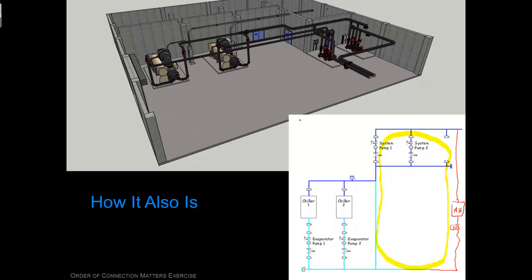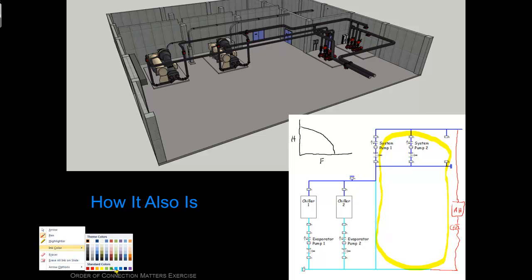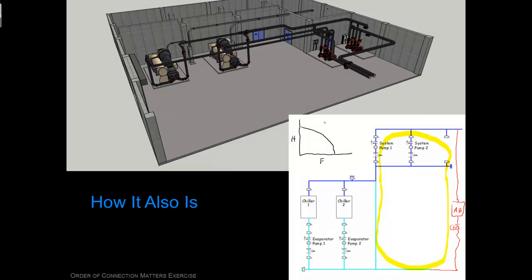So if you remember anything about pump curves at all, it's basically a plot of flow on this axis versus head or pressure on this axis. And for a fixed speed with a fixed impeller size, the pump is going to operate on a performance curve, the shape of which is purely a function of the pump's geometry and the way it's designed. On a typical pump curve, if you were to plot the constant brake horsepower lines, they would sort of go diagonally across the curve like that.